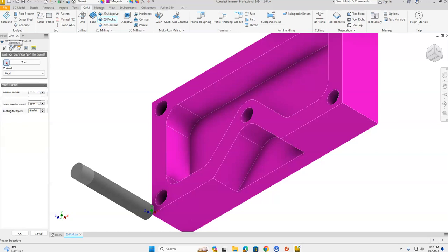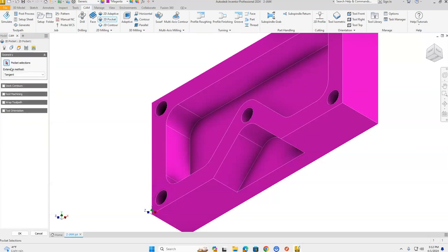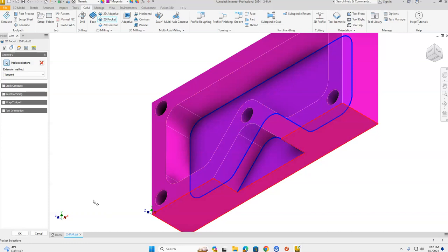We're going to go next and select our geometry in the geometry tab, and I'm going to click this bottom surface here. Make sure you get that whole surface to highlight red, and the back side where this sort of face mask looking shape is. Make sure you're selecting that surface. Okay, after you select those two surfaces, we can go home.